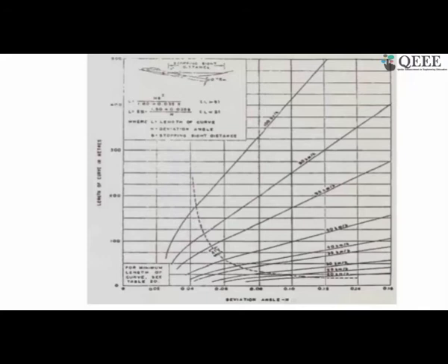Another question I received is: the valley or summit curve increases the effort, so how is it beneficial? Can we alter the gradient? The valley curve is from the vehicle's point of view; it does not increase the effort when going downhill. It is only after negotiating the valley curve, when the vehicle is coming out of it and the gradient is ascending, that's the summit curve. When going towards the summit curve, the effort is actually increased. Once the vehicle negotiates the summit curve, the effort is eased out.